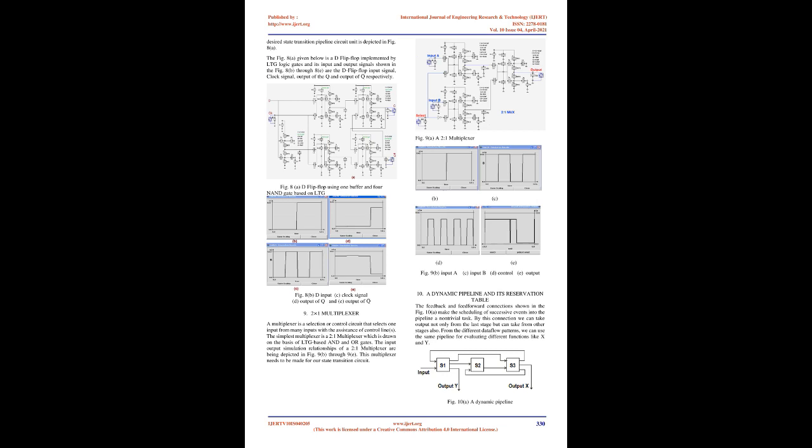Fig. 10c, reservation table for function x. Two state diagrams we have obtained from the two reservation tables are given in Fig. 10d and 10e. A state diagram is obtained for the reservation table in Fig. 10c by using a 7-bit shift register, and another state diagram can be obtained for the reservation table given in Fig. 10b by using a 4-bit shift register. The process of making the state transition diagram is given in sections 13 and 14.